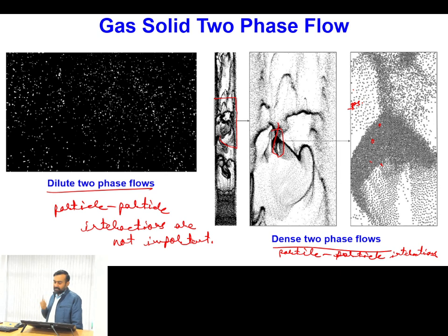So in dense phase flows, if the flow is excessively dense, then gas momentum will not play any role. Majorly, the interaction will be governed by the particle particle behavior. If the particles are sparsely placed, not having any direct contact, only suspended in the gaseous medium, then momentum exchange between gas and particles will be significantly required for analyzing the entire flow physics.